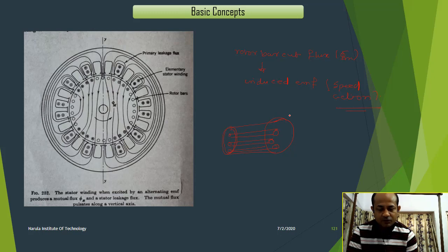So as the rotor is symmetrically closed circuit with the end bars, due to this induced EMF, a current will start flowing through the rotor winding. There is a rotor number of turns NR, and suppose the current is IR, so it will produce ampere turns.